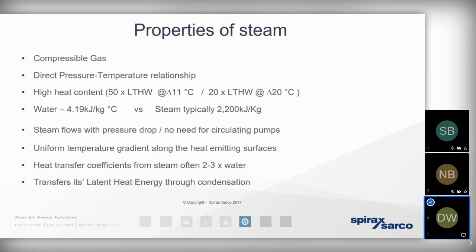We also know that steam is very, very dense in energy compared to other sources of energy, such as low temperature hot water or thermal oils. And we also know that the cornerstone of steam engineering is in the understanding that water, which is the raw ingredient of a steam system, has got a specific heat capacity of 4.19. In other words, if we want to increase a kilogram of water by just 1 degree, we need to add 4.19 kilojoules of energy into it. And because steam is generated at higher temperatures and pressures than LTHW, that explains why there's so much useful energy in the steam, why it's so energy dense.